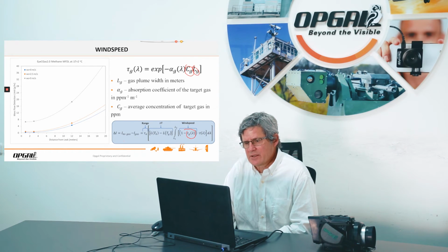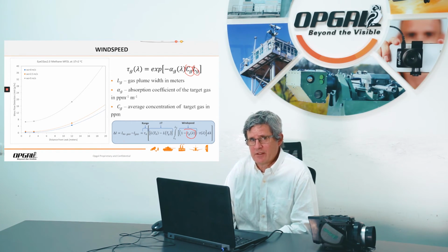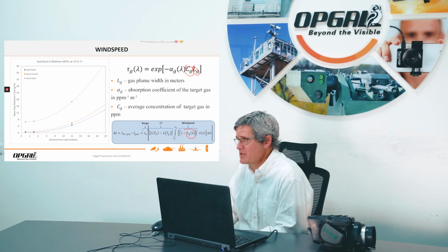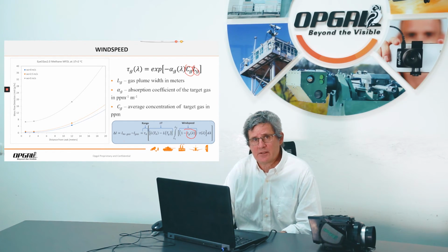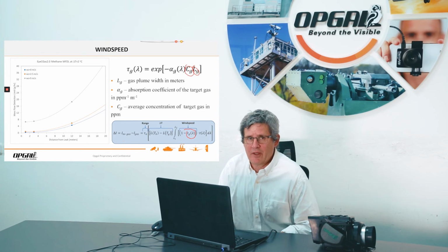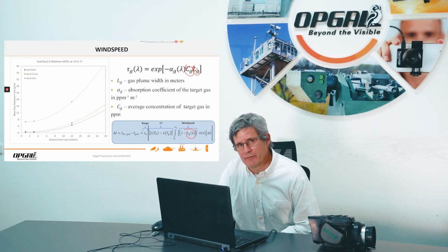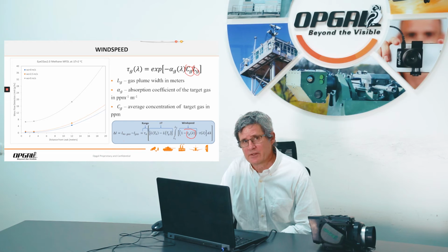To summarize this lesson, I would like to emphasize that OGI camera can be very sensitive. We have defined in several tests, third-party tests, that we can see methane with a minimal temperature difference of 2 degrees from a distance of 2 meters.